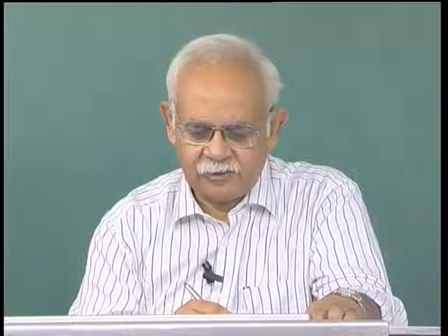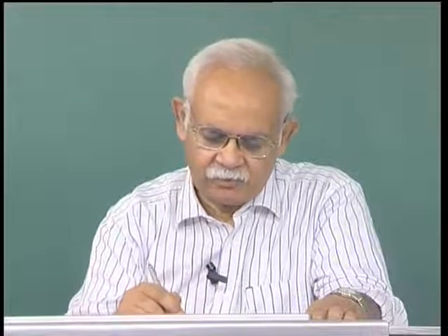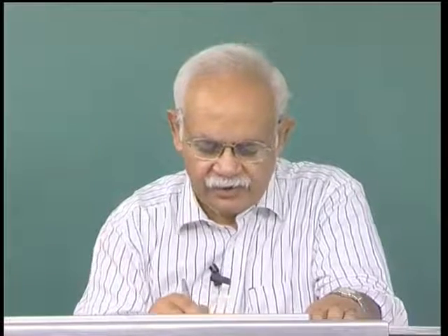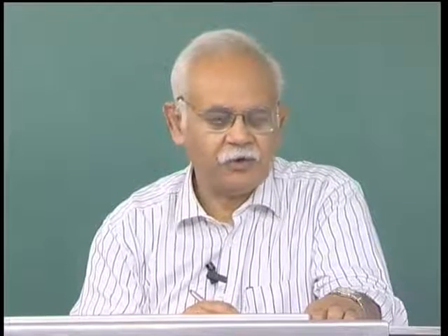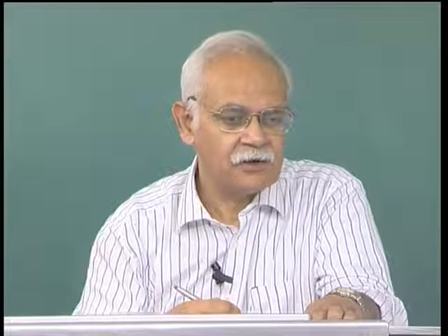So, this is what the basic principle was, that there is an initiation time and there is a propagation time, and if we do not want to bother about the propagation time because of engineering considerations, and we want to confine ourselves to the initiation time, then we need to follow the strategy that we just formulated, that is, at the end of service life, the chloride concentration at the location of the reinforcing bar should be lower than the critical chloride concentration.